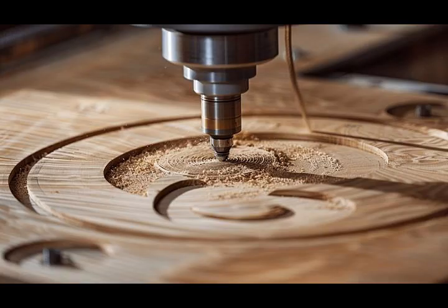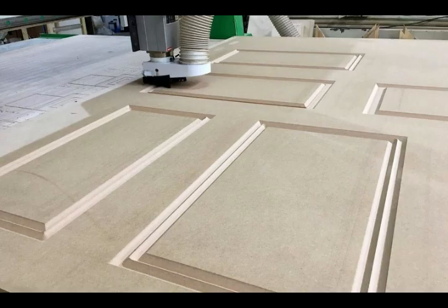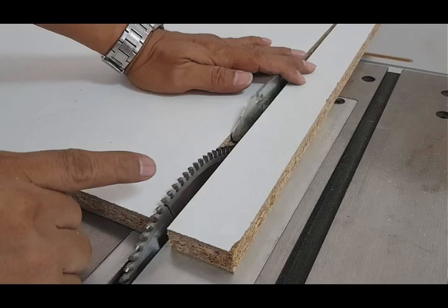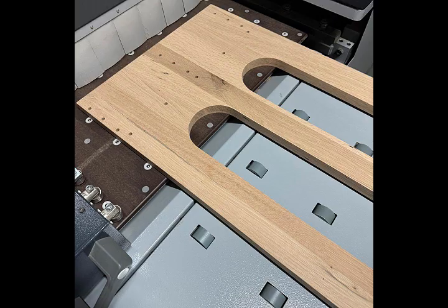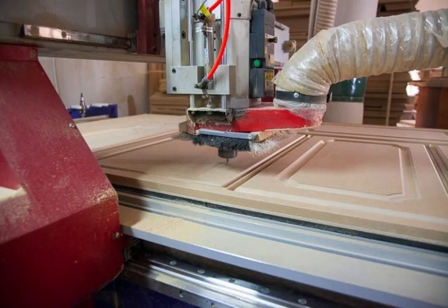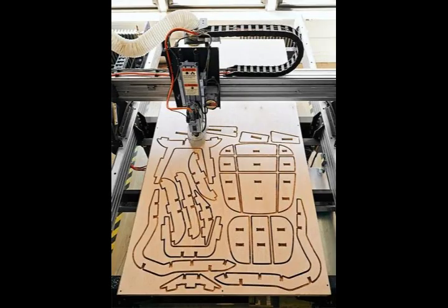Recommended settings for common woodworking materials. Different materials require different machining strategies. Softwood usually allows higher feed rates. Hardwood often requires lower spindle speeds and smaller cutting depths. MDF machines very consistently but produces a large amount of fine dust. Melamine-coated particle board benefits from compression bits and carefully optimized feed rates to minimize chipping. Plywood requires special attention because its alternating grain directions can increase tear-out if parameters are incorrect. Learning the characteristics of each material is just as important as learning the machine itself.